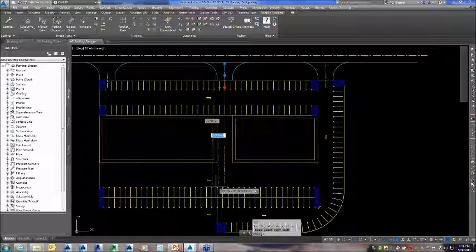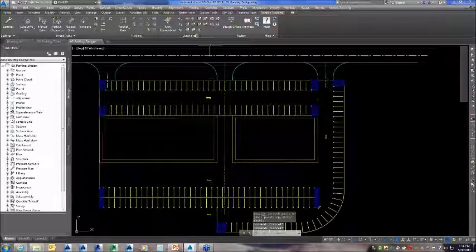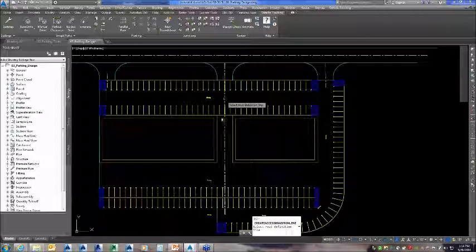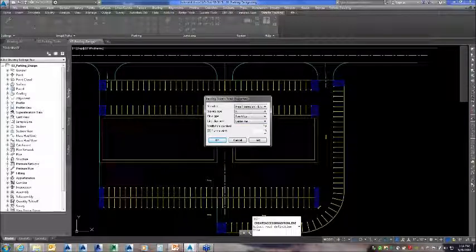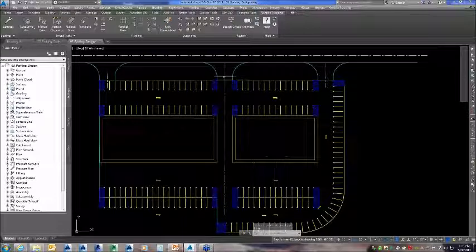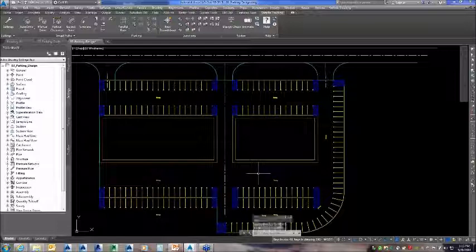If I came straight down, we can pick on extend. And what vehicle tracking allows me to do is I can create an access road from a line. So I'll pick my line, and I'll say I want a custom width of 26. Then I'll select OK. And it creates those bays for me. And again, it's really about how fast you can really create these concepts without having to offset lines in reference to based upon standards that you need to utilize for this concept.